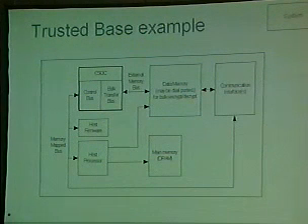Unfortunately, I don't have any way to walk through this diagram without poking Joe in the eye, but I'd be glad to walk through it in the extended deeper knowledge session. Basically, the CSOC there will hold the microprocessor in reset until it can verify its firmware. Once it's verified, it'll let the microprocessor out of reset to boot off of its firmware.